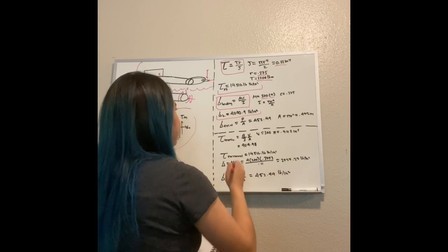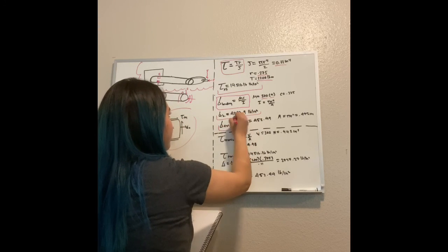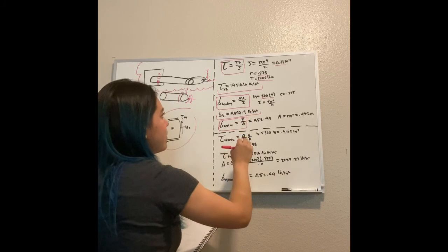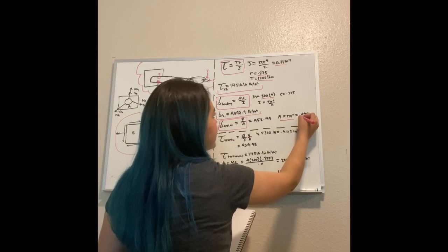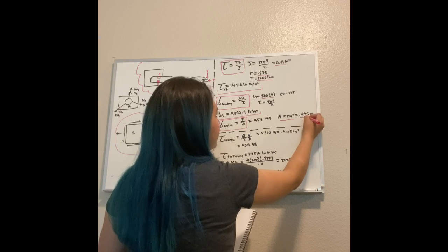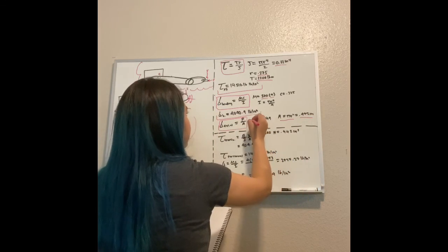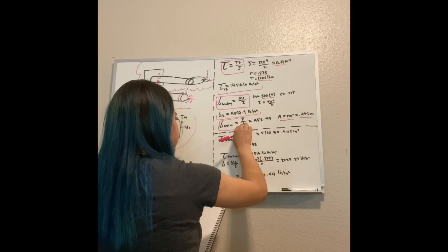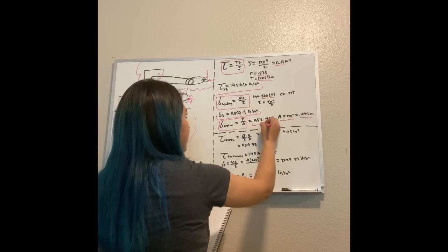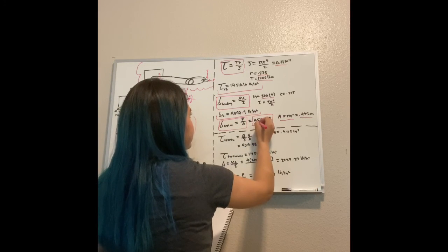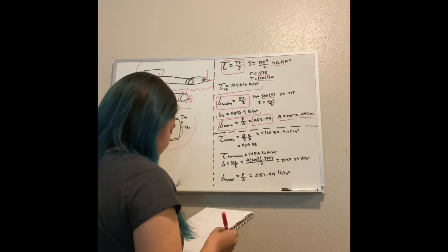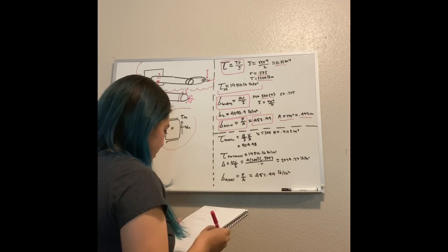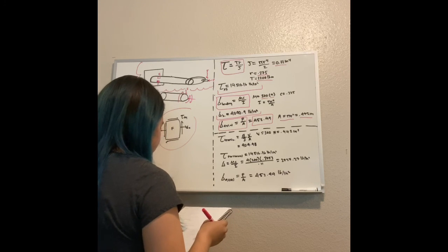And then lastly, we have an axial load, which is going to be P over A. A is equal to pi r squared, and in our case that gives us 0.442. Plugging that back in, we have our axial load equal to 452.49.